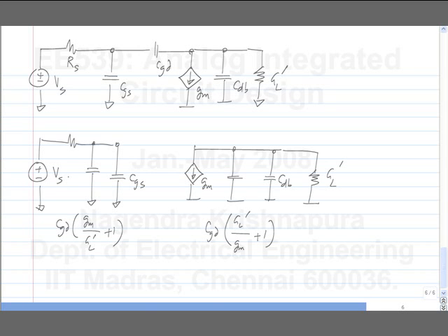So what's the order of this circuit? Second order. But will I get the same answer as before? The zero is not there, and what happens to the poles? Are they in the right place? So I calculated a zero, a low frequency pole and a high frequency pole for this circuit. Already from this I can see by inspection that the zero is not there.